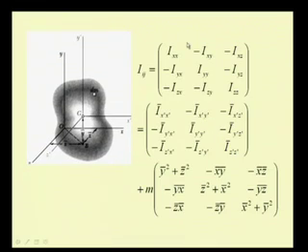Now, let us try to write this in the matrix form, that is the inertia tensor. So, we have this quantity Ixx, minus Ixy, minus Ixz. This tensor is the inertia tensor in the coordinate frame O, x, y, z. Now, each of these terms can be written with respect to the term in the centroidal axis by the parallel axis theorem.